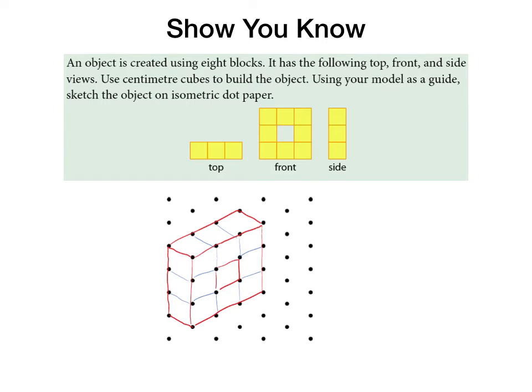So how does your picture compare with this? So the starting point is to draw your front view. My blocks are 3 tall, so I would go 1, 2, 3. And because it's a side view, it's not going to go in a straight line, it's at an angle, and that is 3 blocks deep there. So 1, 2, 3, and 3 blocks high, 1, 2, 3, 1, 2, 3, and then you've got your middle block, which is empty there. So that's my front view.